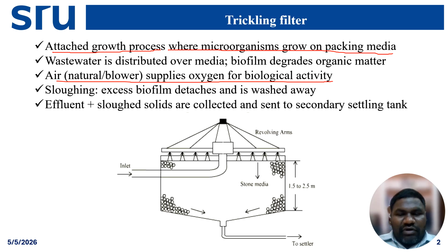Whatever bacteria attach to the media, when the thickness increases, it is automatically detached from the media. That is called sloughing. The effluent plus sloughed solids are collected and sent to the secondary settling tank. Here also, this is the first unit, followed by the secondary clarifier.